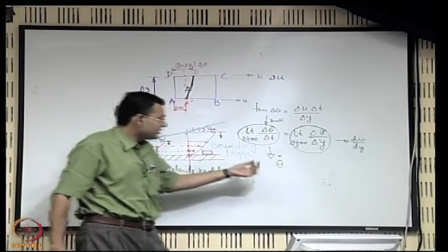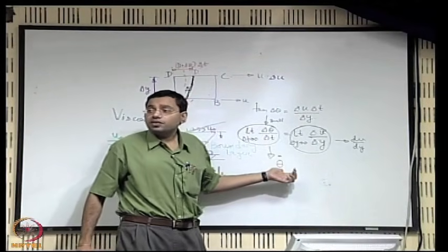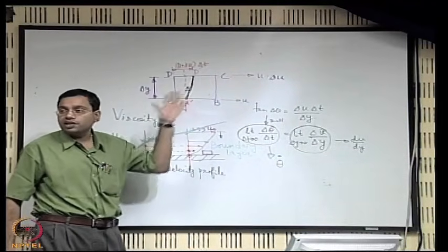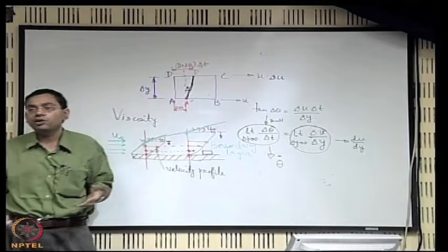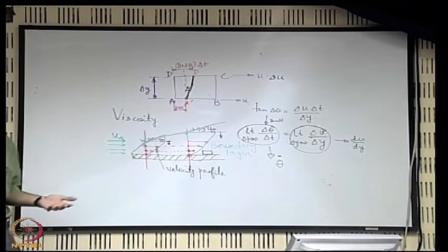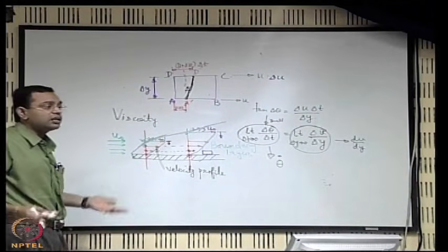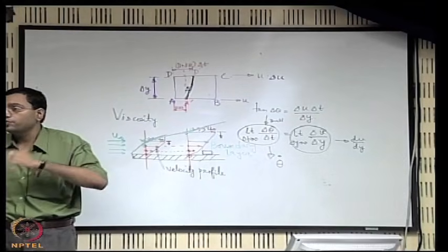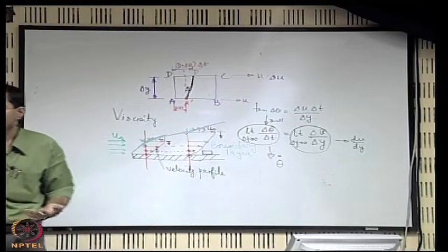In fluids, strain itself is not important, because as we have seen, if you allow time it will be straining more and more. So obviously if you want to quantify strain, it becomes a kind of redundant exercise. You allow more time, and under shear it will be straining more and more, because fluid is continuously deforming under shear.